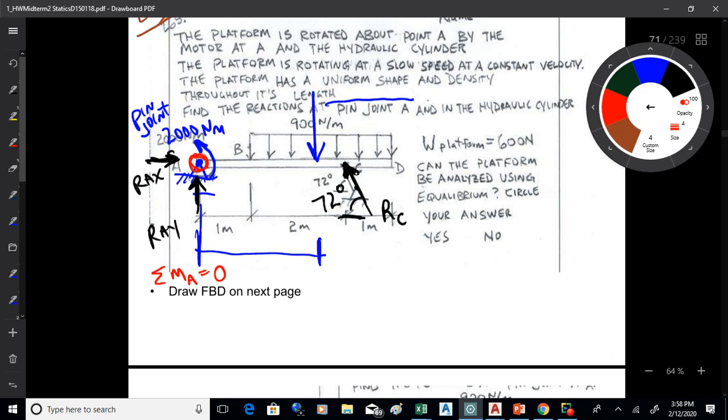So if you do that, you need to include the couple. Do you include the moment arm with a couple? You don't, okay? You just put that couple down there in that blank space I've created because the moment arm is already there. It already has the moment arm attached to it. You don't need to include any sort of moment arm, and that one doesn't even have one.